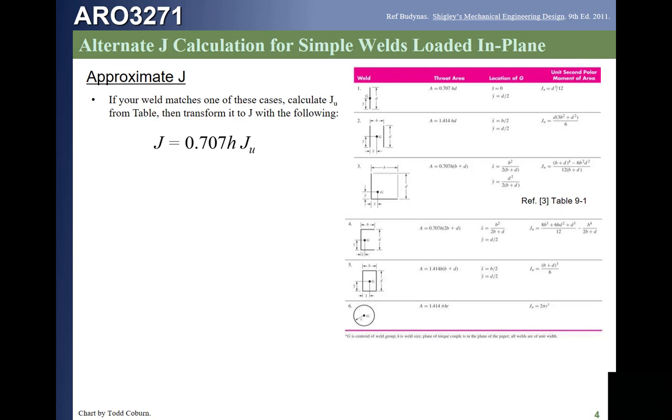We can see it's located from the lower left corner of the weld, which is fine as long as we find precisely this weld. If we find a different weld, for example an upside down L or a sideways L, then that will change the reference point from which the X bar and Y bar computed in these equations are referenced.